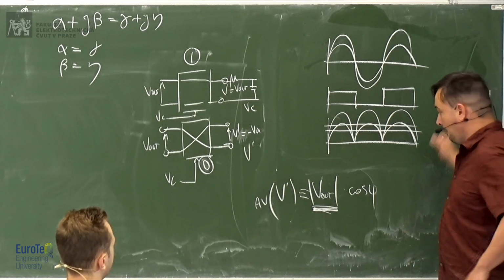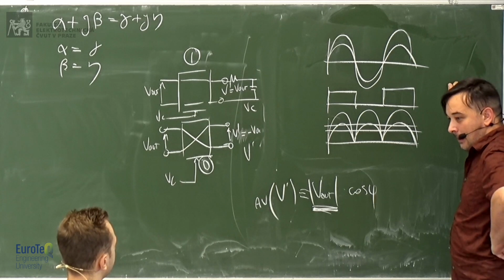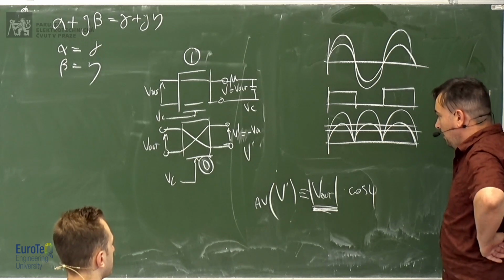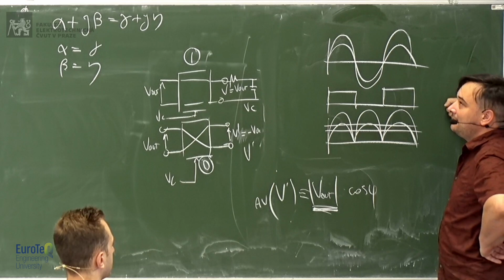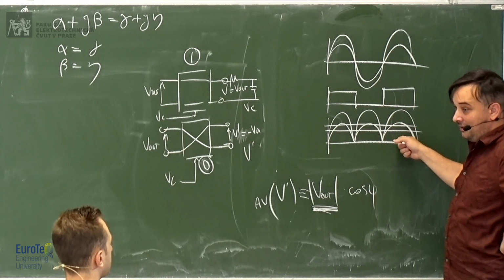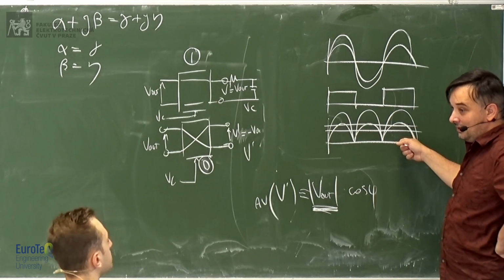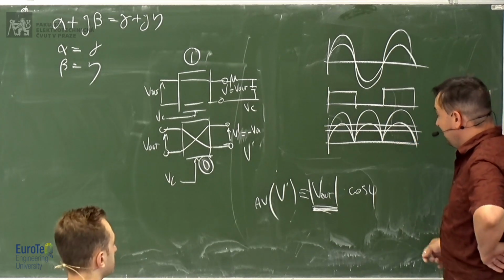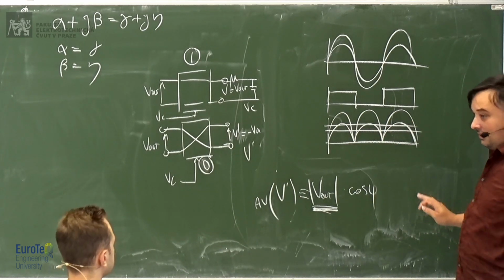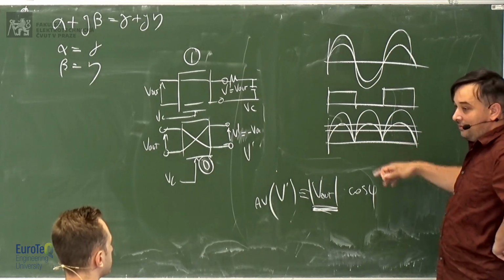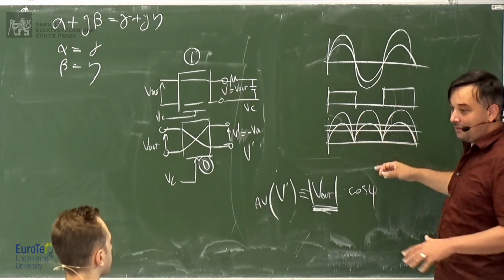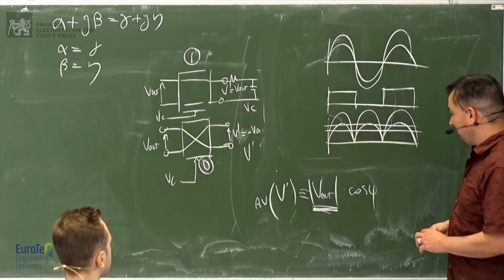But it wouldn't be V out RMS? Because if you put it in absolute, that means it's your peak. No, in this case, this will be the rectified mean value, by definition, not the RMS. Careful: the rectified mean value, so it's the value of the rectified sine wave. In this case, it's not connected to RMS. This is quite important because if you have different waveforms, you have different considerations to take. But if you have a sine wave, then you know the ratio and so on.